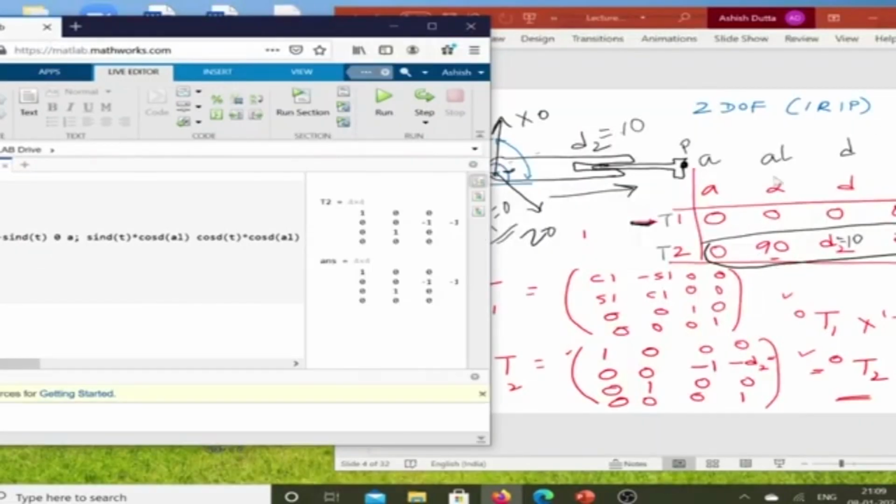So if you look at the DH parameter table here, this is the matrix itself. And what you can do is take each row of the matrix, put it into that and get your corresponding matrix. So what you're dealing with are matrices now. As we finish our forward kinematics and inverse kinematics, we'll look at a little more complex way of writing programs in which we will treat the DH parameter table also as a matrix. Each time we'll be taking one row, putting it into this, getting the corresponding matrix, multiplying them out, and then understanding how it works.